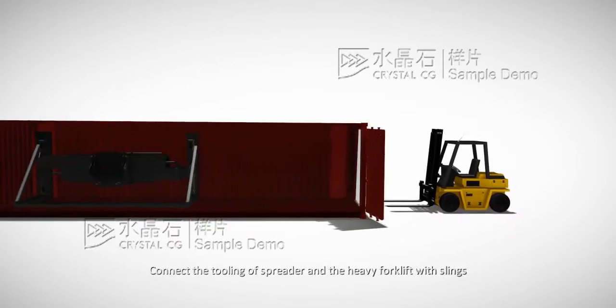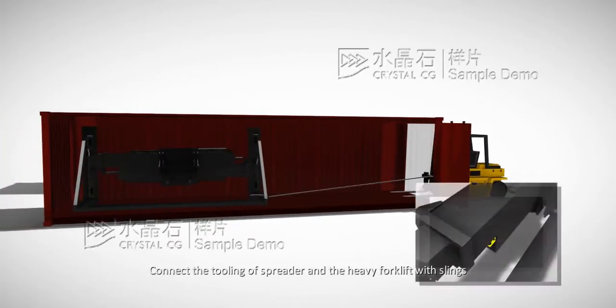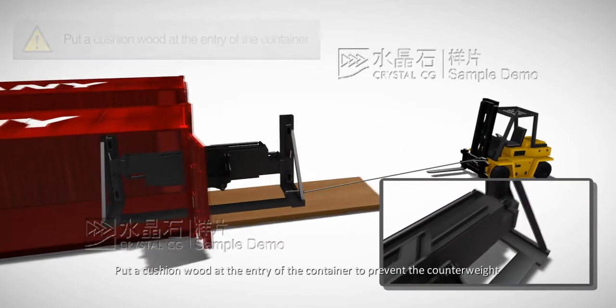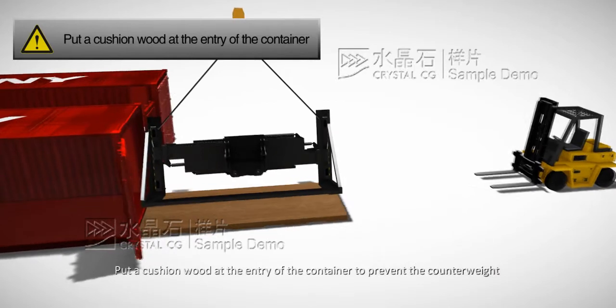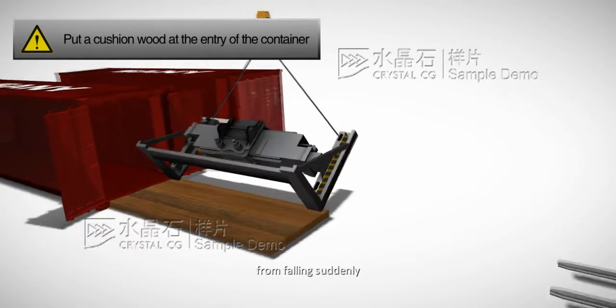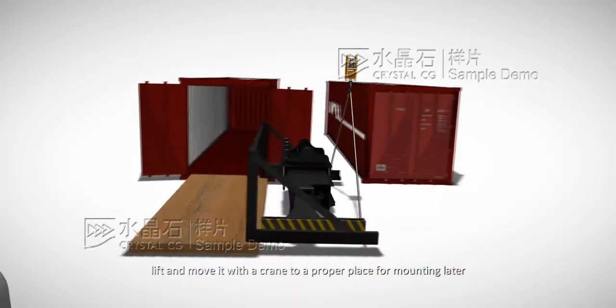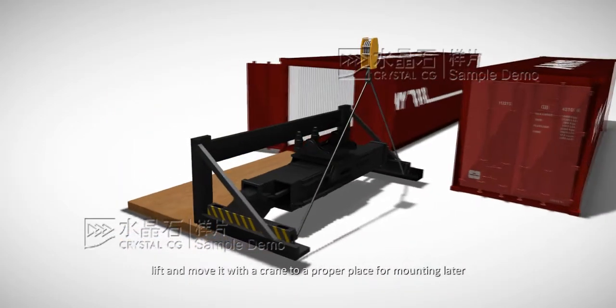Connect the tooling of spreader and the heavy forklift with slings, and drag it out. Put a cushion wood at the entry of the container to prevent it from falling suddenly. After dragging it to a certain position, lift and move it with a crane to a proper place for mounting later.